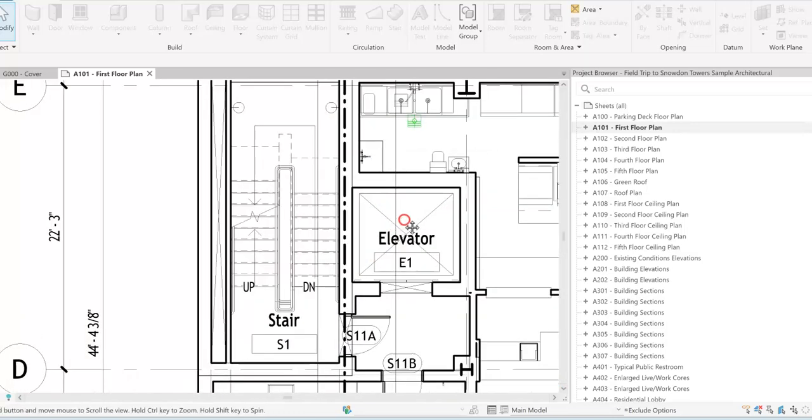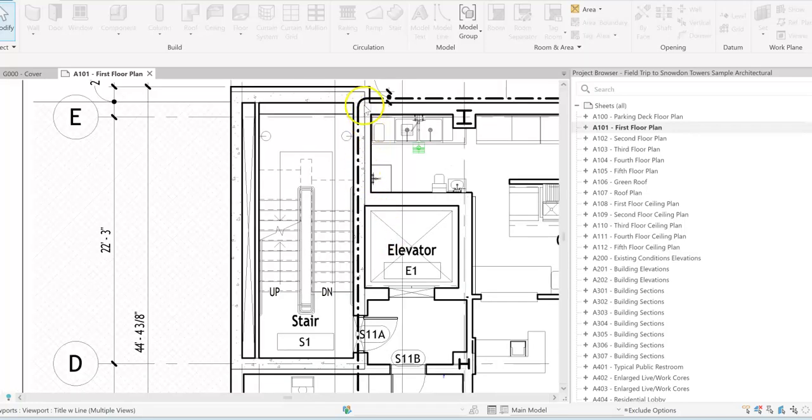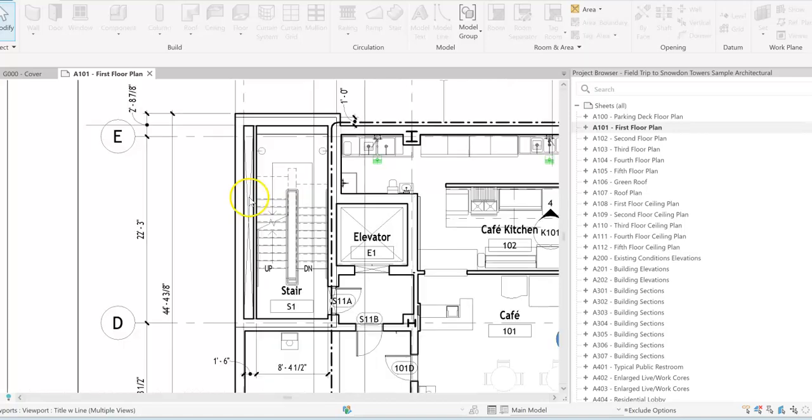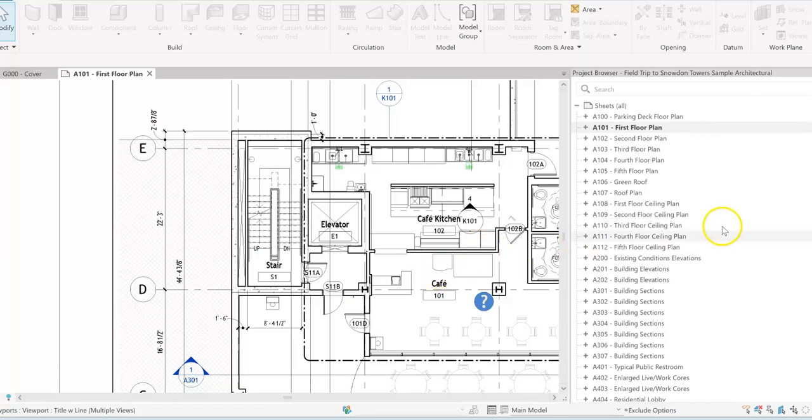You can see the stairs, and you can see how thick the stairwell is and where it is located. It looks like we have a vent coming up through here. Anytime you have an X, that usually means it's open, and as you can see in the elevator, that means it's traveling vertically. My thought is that this might be a stack letting air out of the lower floor, which was a parking garage, but more information would be needed to really determine that. So let's take a look.